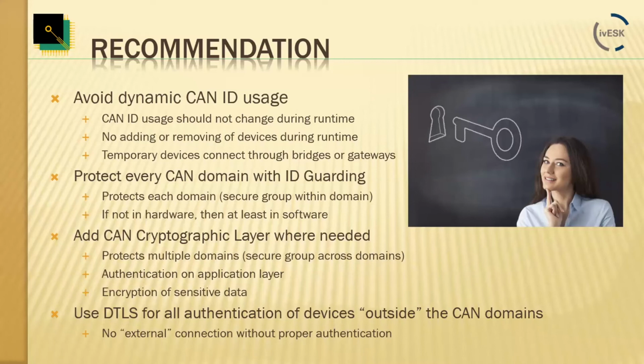Literally, as I said, the very first easy implementation could be that whenever you transmit something, add this identifier to a list, saying, oh, this is a CAN ID that I use for transmission. And whenever you see this CAN ID coming back from the network, trigger whatever your alarm event is, saying, okay, something is wrong here. Somebody else is using my CAN ID. This is so simple in software that everyone should do this as a first step.